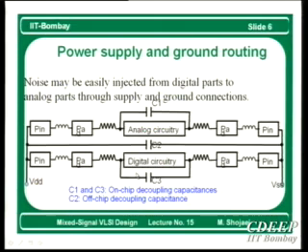So decoupling capacitances should be large enough. Otherwise, they will get discharged quickly and they cannot maintain the voltage which is supposed to be maintained across the circuit. That is an important point. And the current which is drawn from these capacitors also should be large enough. Therefore, these capacitors should be large. So putting decoupling capacitance is quite a normal tradition in all mixed signal and fully digital circuits. And it's very easy to do.